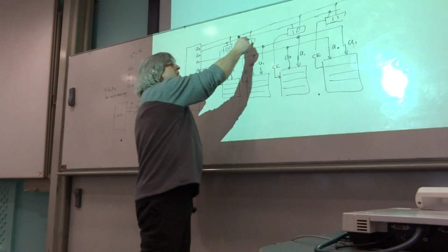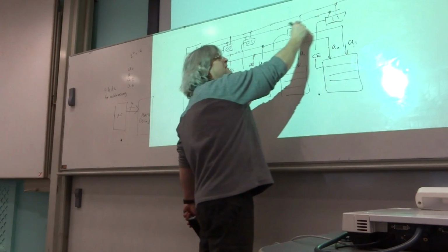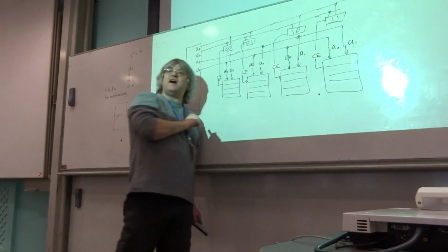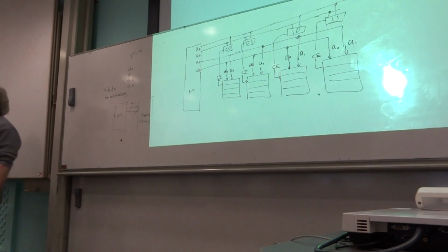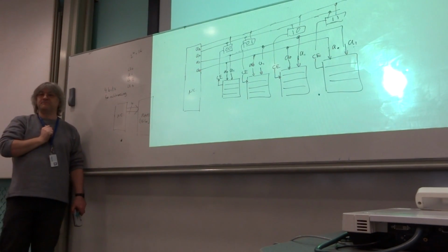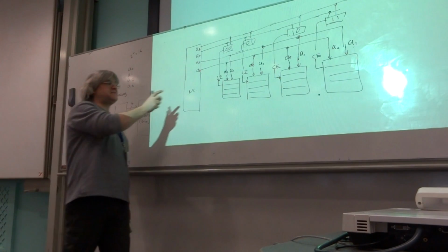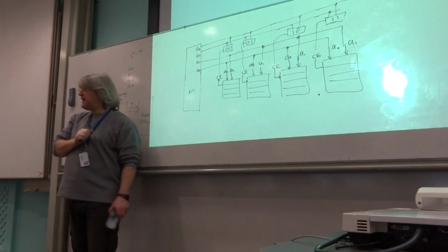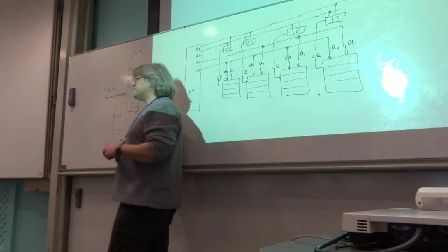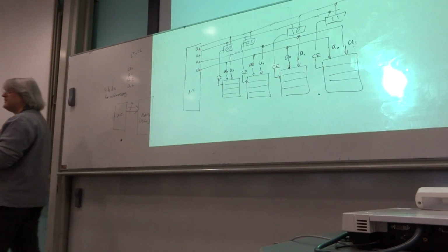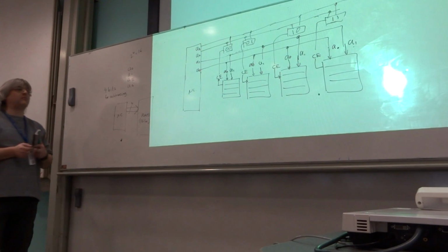That bit of logic in here that I've used to make sure that holds true, that at any point in time, at most, only one of them can be switched on, is address decoding. So that's what this particular topic is about: what do we put in here to make sure that the things are switched on in the appropriate way.